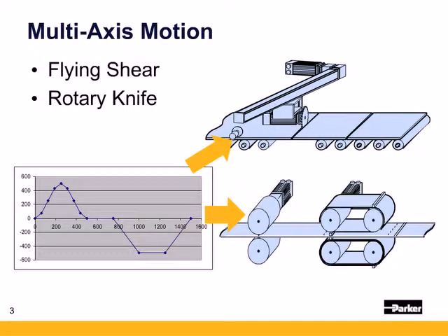Multi-axis motion is made easier with the ACR9000 programming language. Here is an example of a machine with two parts. The first is a two-axis flying shear with belt-driven actuator carrying the material cutter with a load-mounted encoder. The other part of the machine has a rotary motor that is either material feeding nip rollers or could be printing labels onto material and then cutting the labels to length. The entire machine could be running on a continuous cam profile.